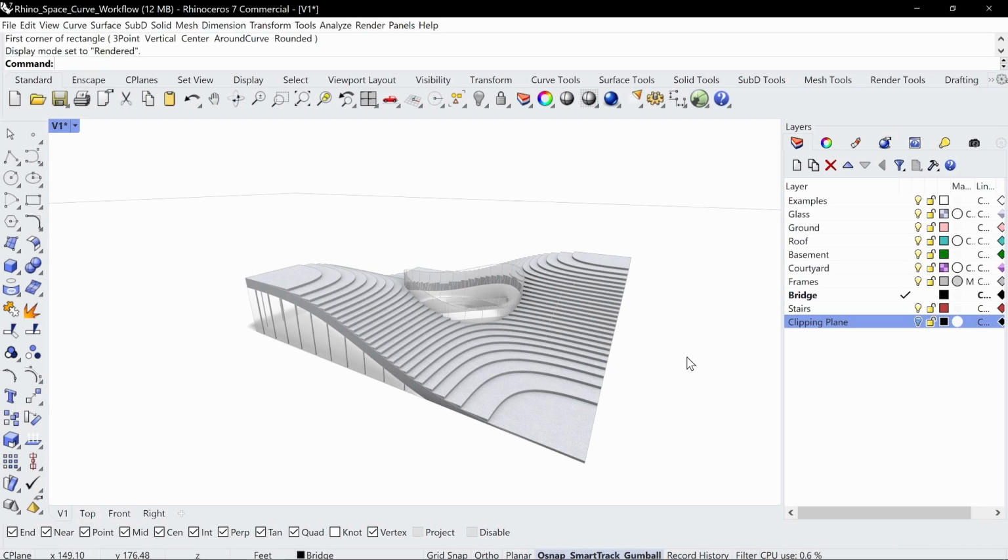So in the last video course, we covered how to create a landform architectural design from a basic surface. And we're going to continue working on this design. What we're going to do next is create an open to below space from the ground level down to the basement level. And then we're also going to create helical stairs, 2 sets of helical stairs and a polar array. Later down, we're also going to create a structure for the roof, just to show you how we can maybe make the structure a little bit parametric with maybe like a very simple definition in Grasshopper.